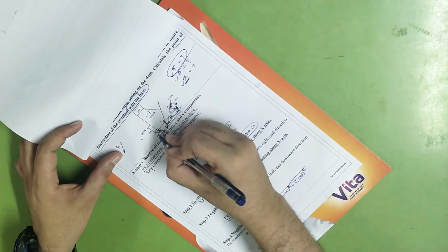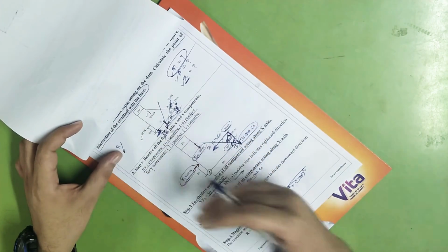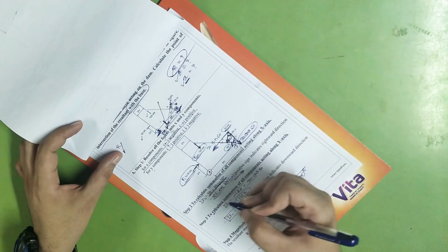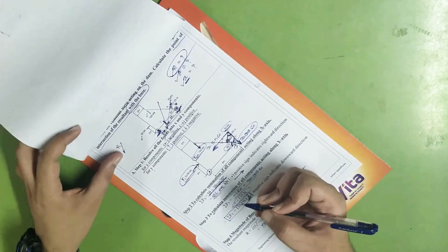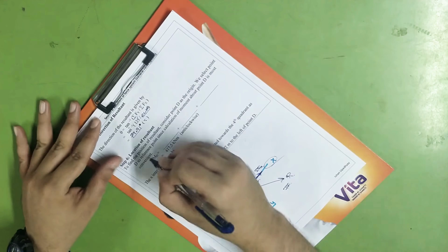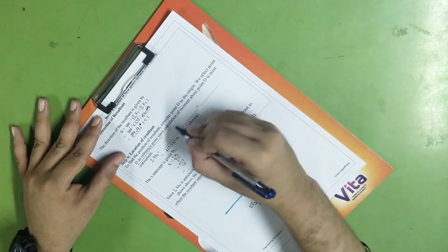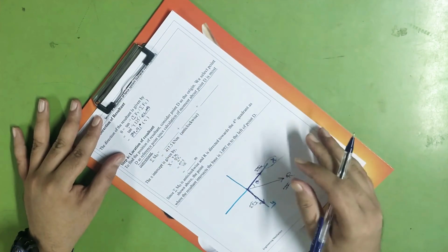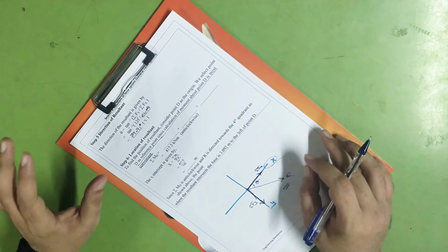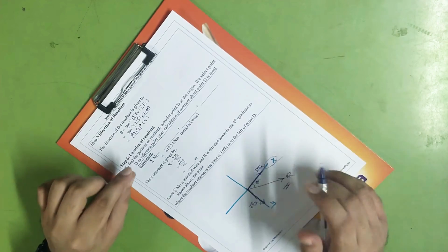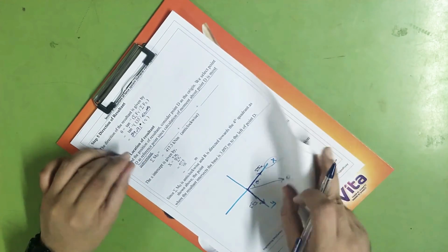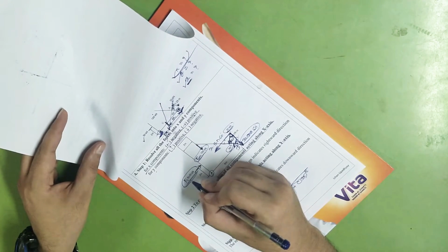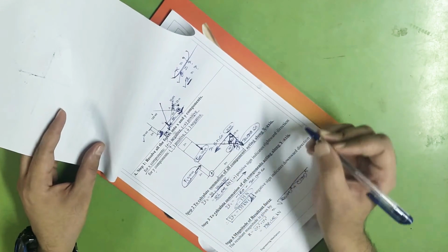So rather than going for point O and making it more difficult, we can make it simple and go for point D. So now we will prefer D as the reference point, since the calculation of moment about point D is the most convenient, in simple language, because the distance is given to you. So we'll go for summation of M about D. For this, we have to find the moment about the 1, 2 and 3 forces.